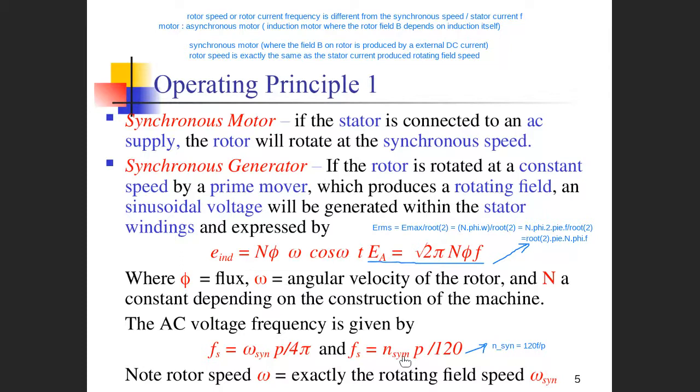So we make the rotor turn at 500 rotations per minute to achieve 50 hertz of generated electricity. And we can increase the number of poles to 120, so that we need a rotation speed of only 50 rotations per minute, about one rotation per second.